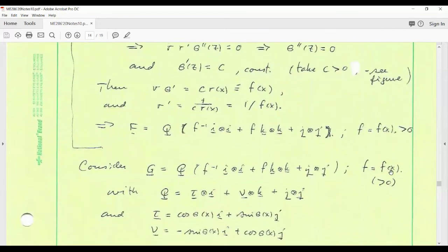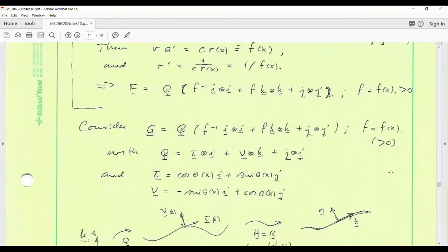Let's assume our plastic deformation, evaluated at the midplane again, has this structure. So if our plastic deformation has the same form, we would expect the plastic deformation to tend to induce a flexure of the plate itself, right? So let's look at that kind of plastic deformation. This has a determinant of 1, so that's consistent with plastic incompressibility, which is what you would get from a standard flow rule, right? So it's plausible, at least from that point of view.